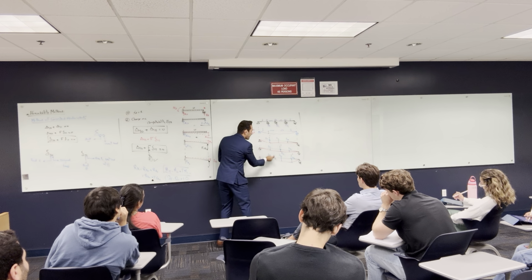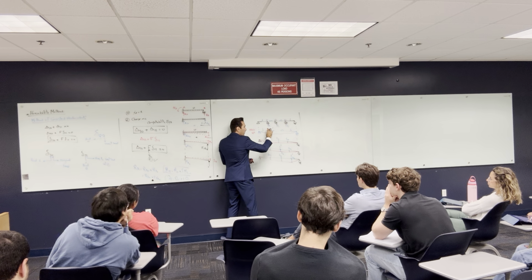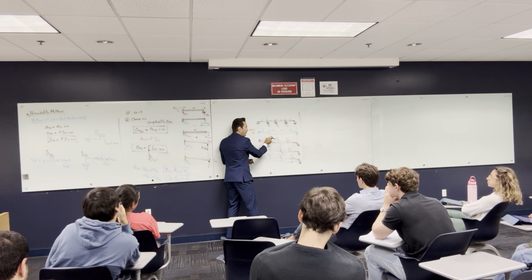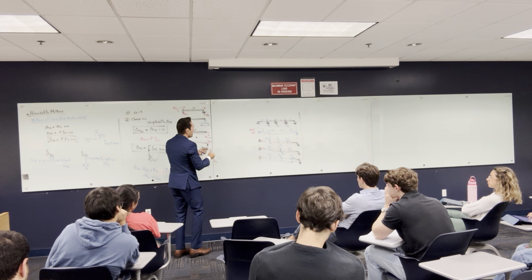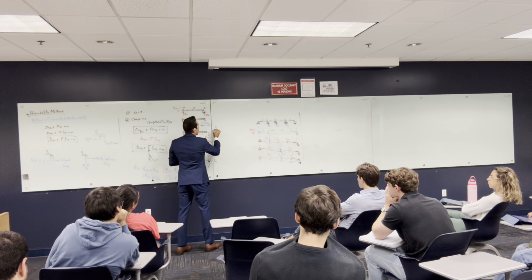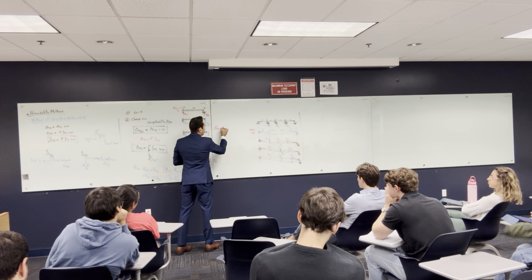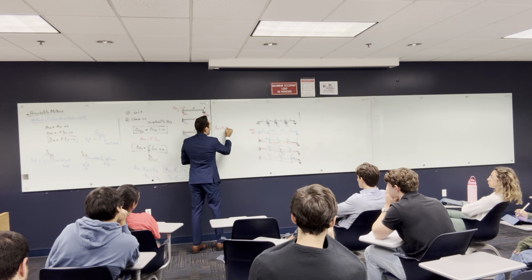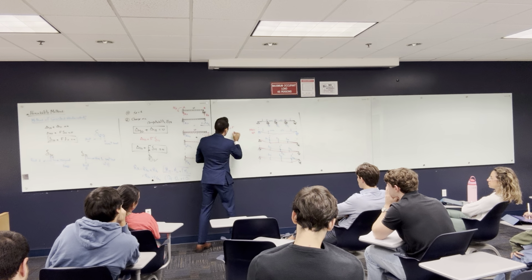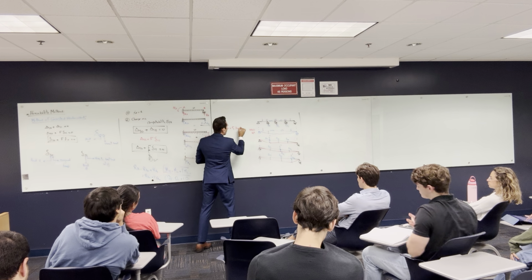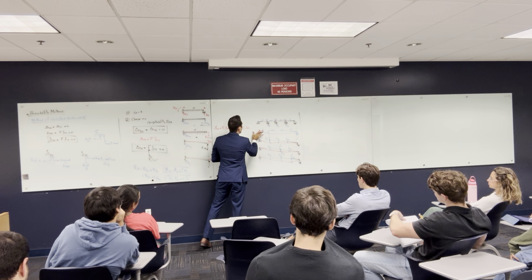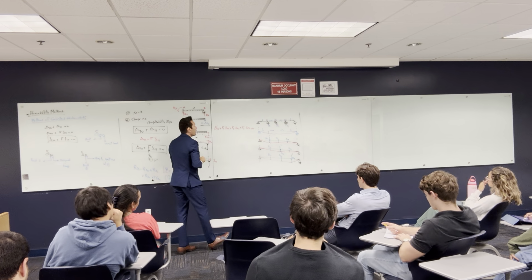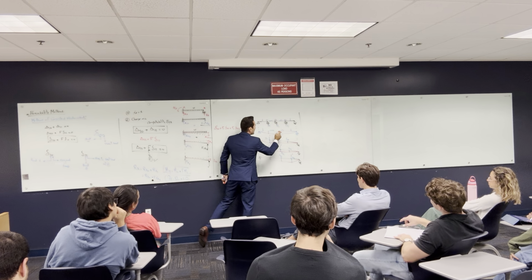So delta here should be equal to F1 multiplied by this delta, F2 multiplied by this delta, F3 multiplied by this delta. Okay, so this is our first compatibility equation: delta 1O plus F1 multiplied by delta 1,1 plus F2 multiplied by delta 1,2 plus F3 multiplied by delta 1,3. And this should be equal to 0. That's equation number 1.